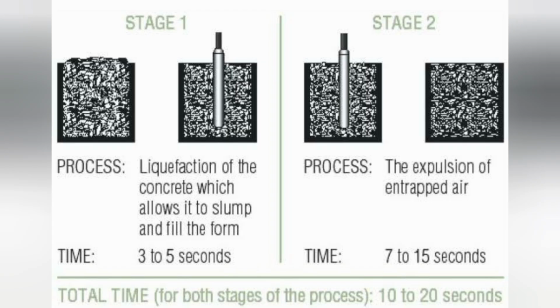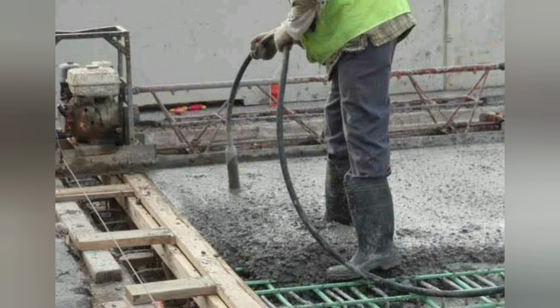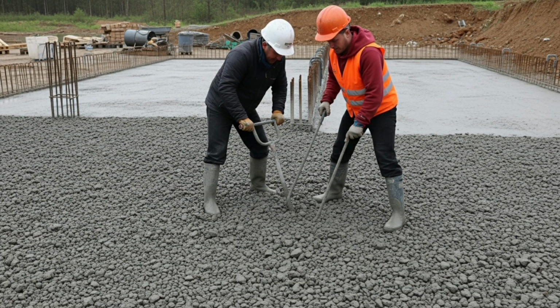Concrete, as placed, is full of air bubbles, typically 5% to 20% entrapped air. The goal of compaction, whether by vibration or rodding, is to expel this entrapped air to create a dense, homogeneous mass. For every 1% of entrapped air you leave in the concrete, you can lose about 5% of your compressive strength. Think about that. If you have 5% voids due to poor compaction, you've potentially lost a quarter of your design strength. The concrete will be honeycombed, porous, and vulnerable to water and chemical ingress.